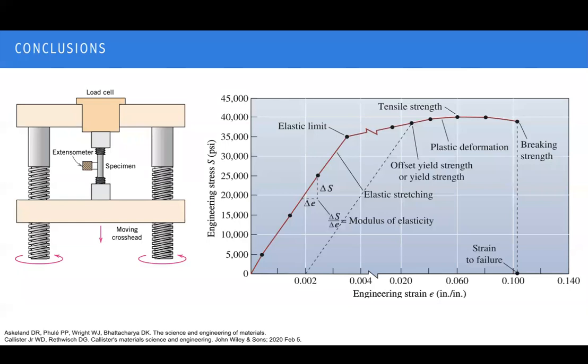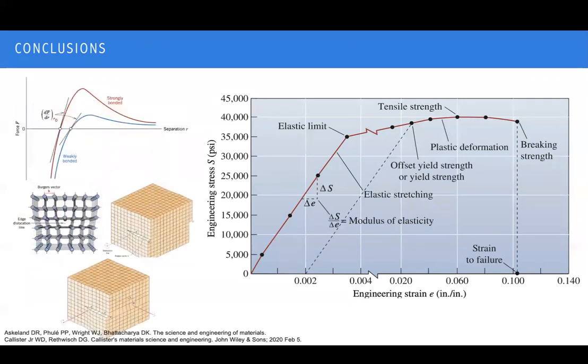To make the conclusions about the whole presentation, the first one I talked about was the tensile test, and the tensile test gives the stress-strain curve. The first thing is the elastic property of the material, defined by the modulus of elasticity, and then going to the elastic limit, there will be the yielding, giving the resistance to plastic deformation.